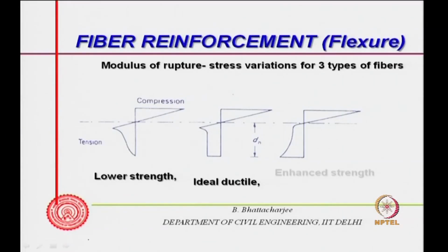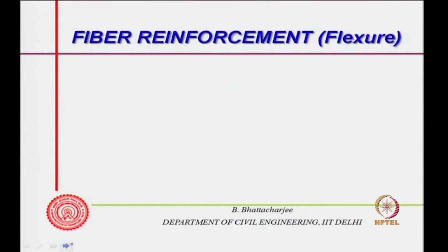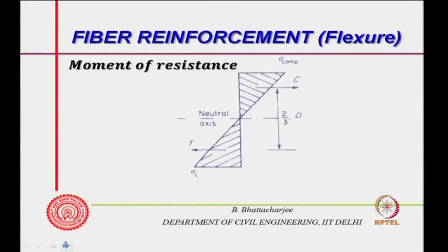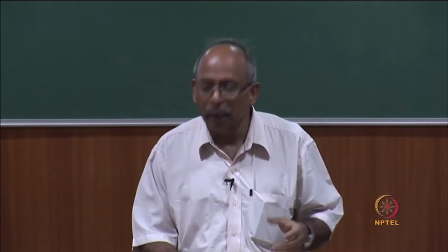Here it is strength enhancement, enhanced strength, but in any case the deformation available is significantly large, the corresponding strain available will be significantly large. So, let us look at the moment of resistance for no fiber reinforcement, for plain concrete.